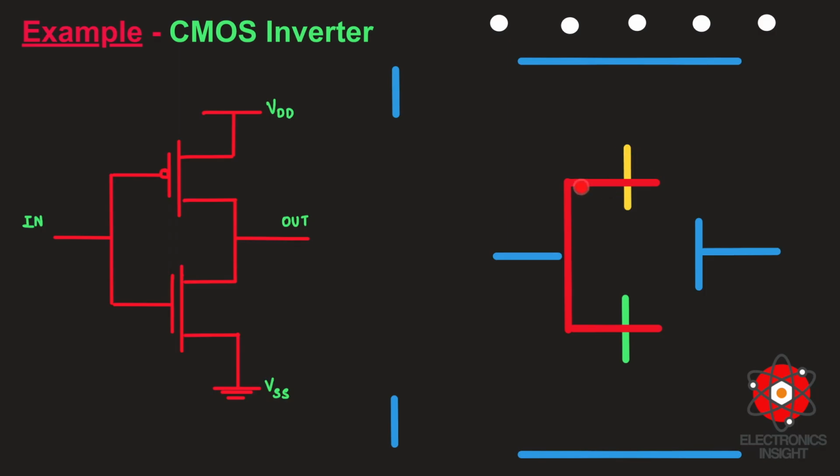The transistor one end is going to be this gate, and this end is going to be the source, because we obviously know that the source of this P diffusion layer has to be connected to the VDD layer, which we have fixed earlier. And similarly, the source of NMOS is going to be here, because that has to be generally connected to the ground rail. And therefore, the left out terminal is going to be the third terminal, which is the drain terminal of PMOS and NMOS.